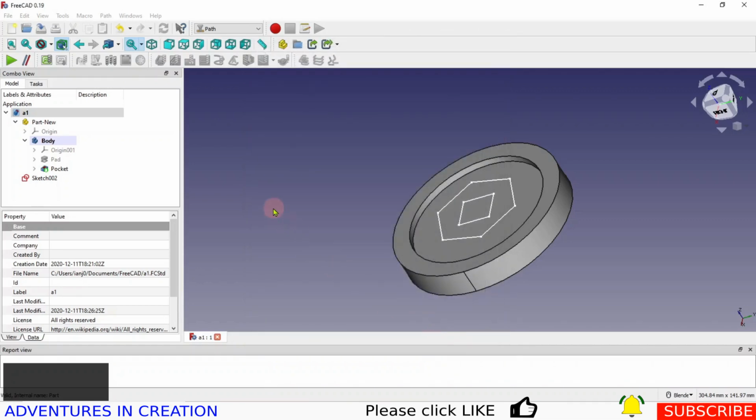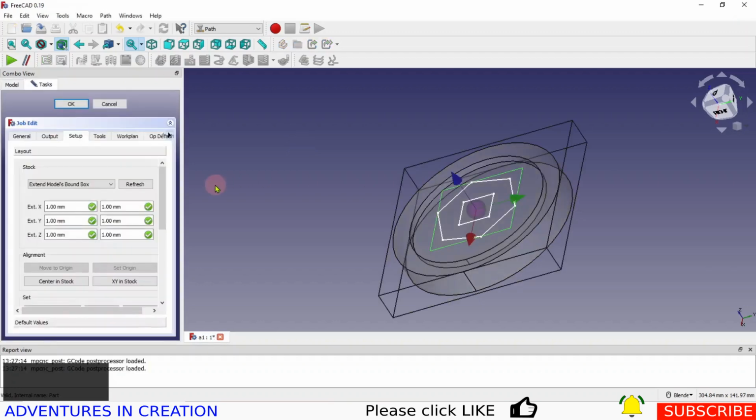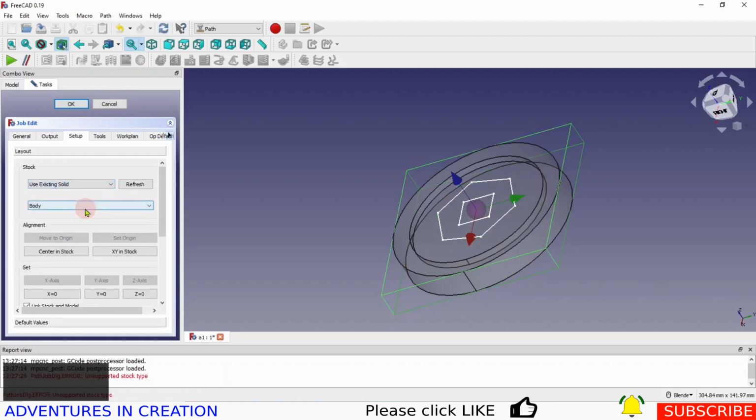So we say OK, and the first thing we want to be able to do is a pocket. Oh, there you go. And so we're going to want to create the pocket. So let's go through, review our job first, make sure everything is the way we want it to be. I'm actually going to tell it to use the existing solid rather than a bounding box. So that's the first thing.